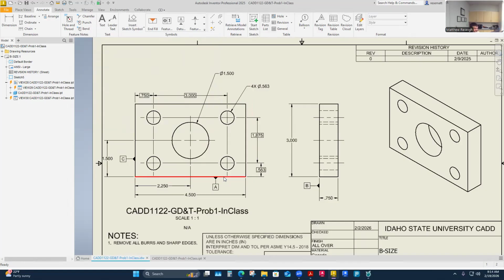B, maybe I'm not inferring much from B, but I really am inferring, by selecting datum B over here and how it relates to these holes, that the hole axis is going to be perpendicular to it. I think it's just understood that if I establish a datum B that's perpendicular to the hole axis, and I use B as one of the controlling datums when I build out this GD&T symbol, I'm inferring that the hole will be perpendicular to B without even saying the perpendicular sign.